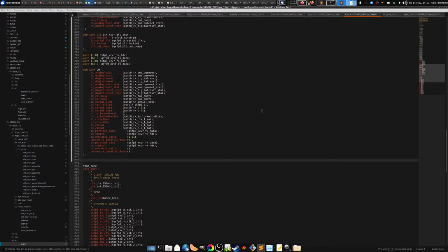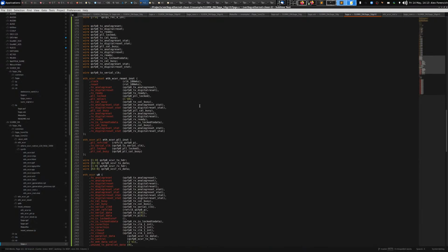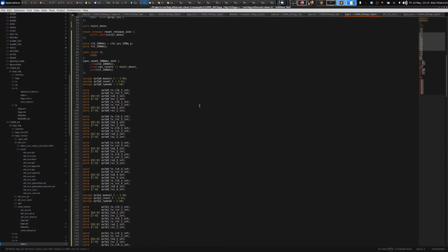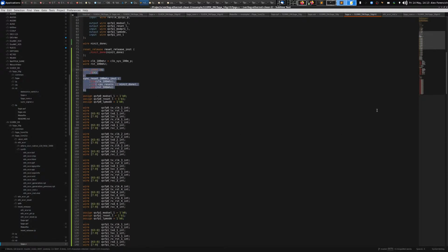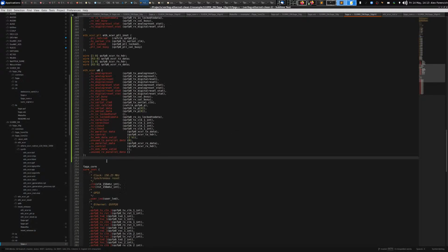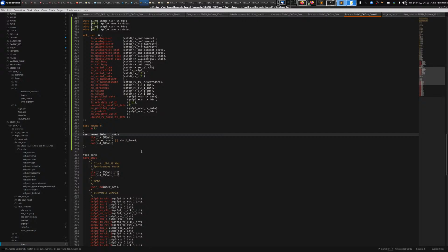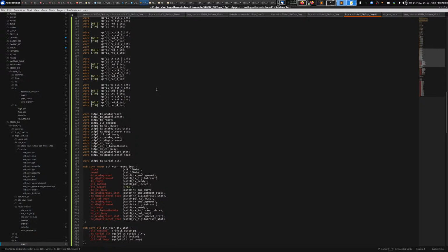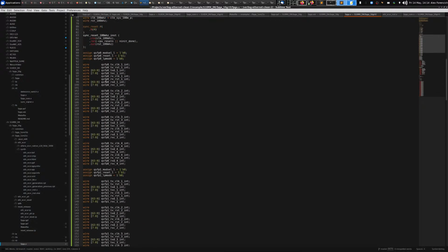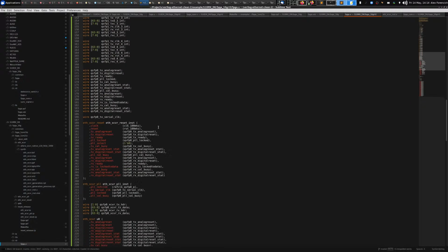All right, let's see. So now the next thing I need to do is pass a couple of clocks around, generate a couple of resets, and then instantiate the PHY core. We'll see what that looks like. All right, so the first thing I'm going to do is grab my reset controller that I have up here, and paste it down here, and I need to use this for both the TX and the RX. So this is QSFP0 RX. All right, what did I have up here? This is QSFP0 RX reset core.